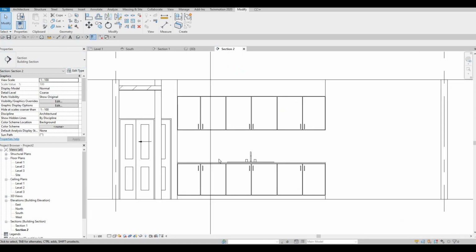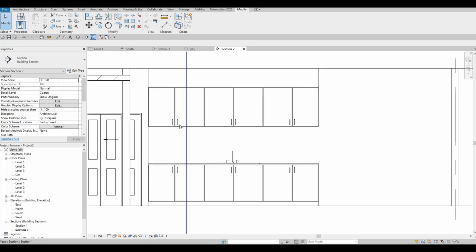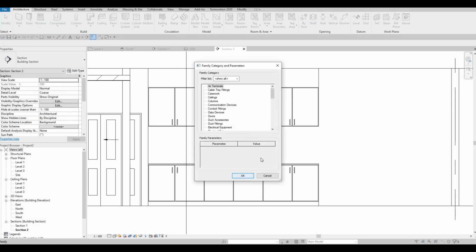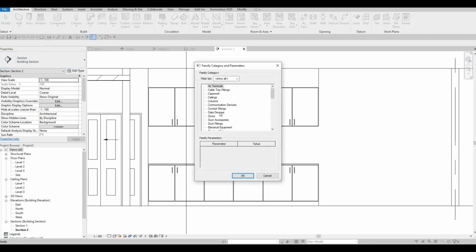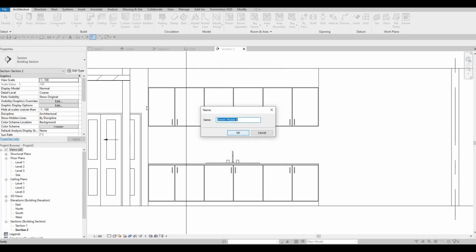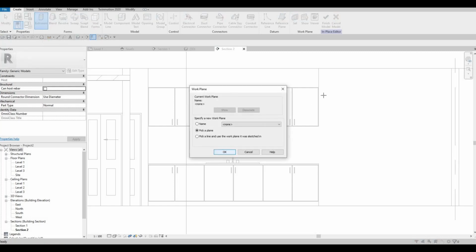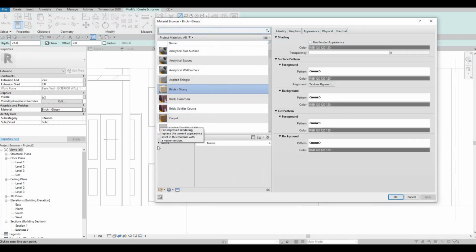So we've done here. Maybe the last thing I'm gonna do is add in a backsplash. So what you could do is same thing, model in place, press O, cancel this. You need to be on generic model. And then we could add in an extrusion, pick a plane, which is this wall. And then we could add in a mosaic tile.